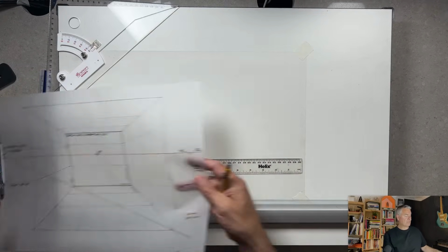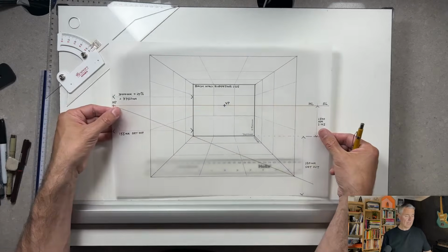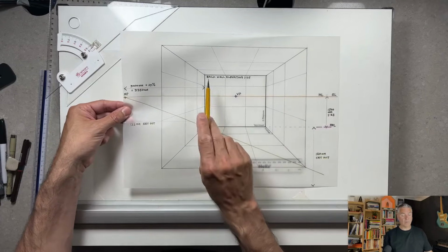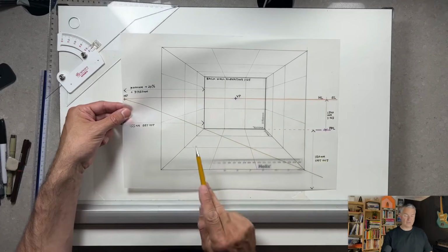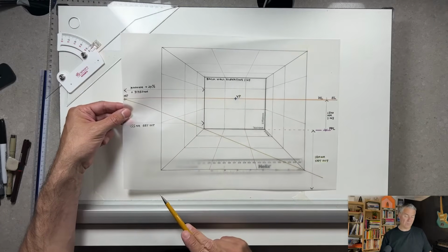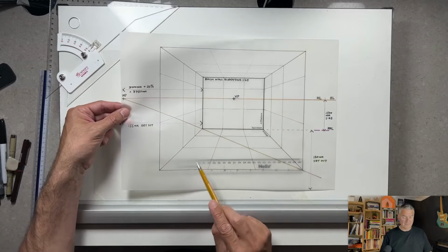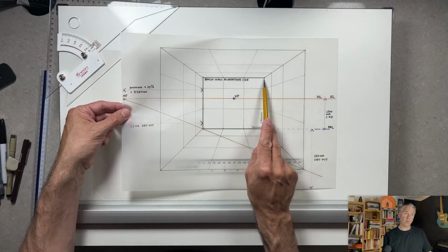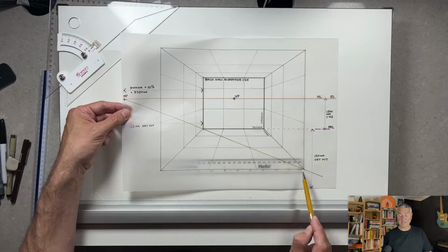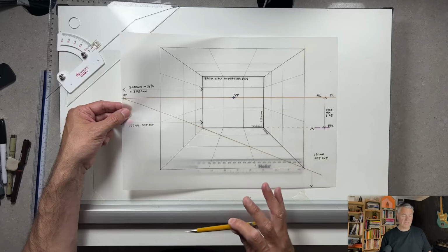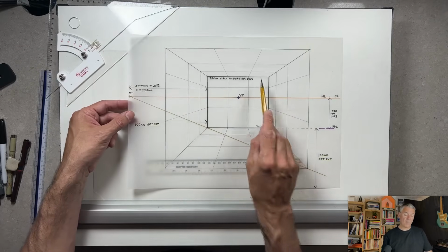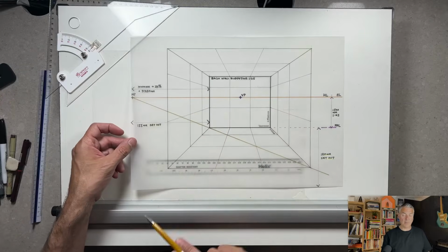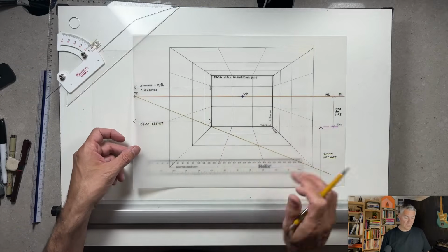As you saw before, I've already drawn this out, and we'll be drawing this now step by step. But ultimately, what we'll first do is draw the back wall, basically the wall elevation of our space. So our space is 3 meters wide by 2.5 meters tall, and it's 3 meters deep. So it's a pretty small space, and we'll use scale 1 to 25. But the first thing we need to do really is to set out where we want to draw this back wall so it all fits on the page.